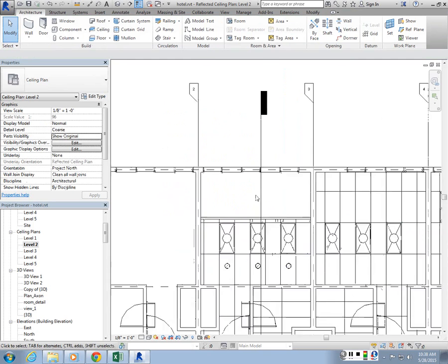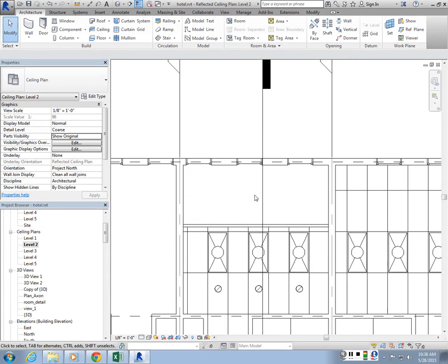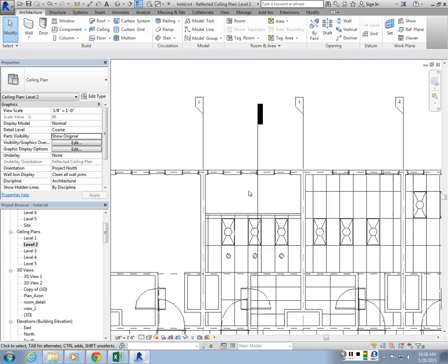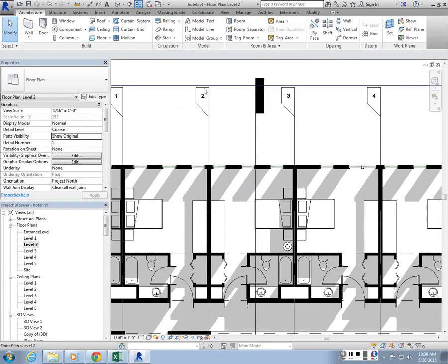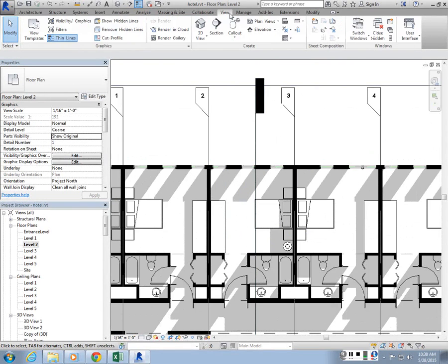And the advantage of that is if you have tons of interior lights in the scene and you just want to make one interior shot, let's say you want to do an interior rendering for this room. So let's create a camera here. Let's go to view camera.